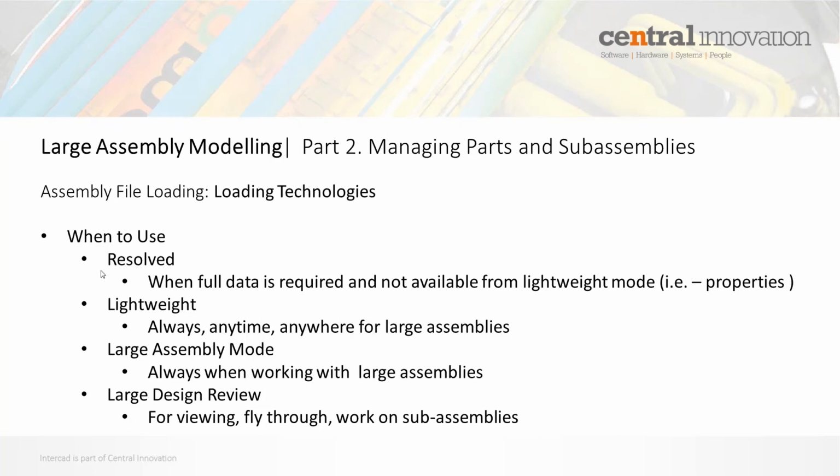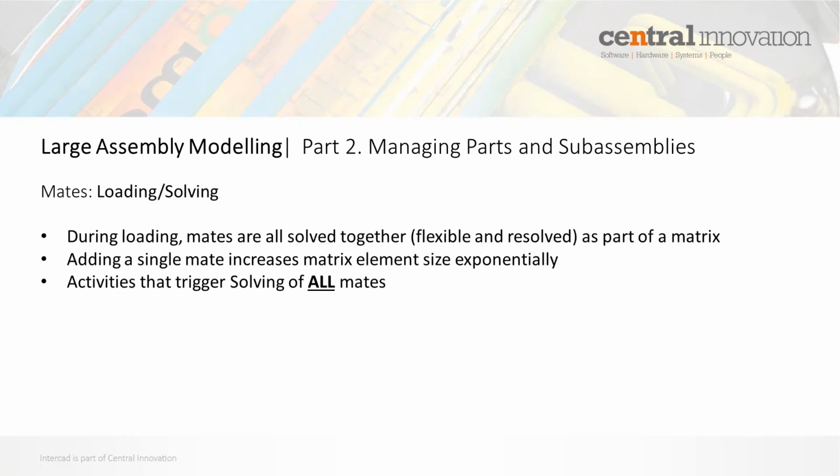During the loading process, one of the most critical steps is step 3, to locate the files and the application of the mates. So if we start talking about mates now, the loading and solving of mates. During loading, mates are all solved together, flexible and resolved as part of a matrix. If you have a look at the mates folder in a SolidWorks assembly, it's just one big folder. Now you can put subfolders in there, but they're all effectively one big matrix of numbers.